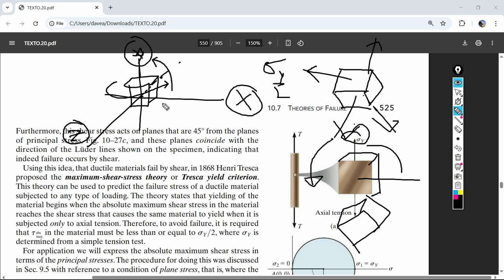Nothing changes there though. So yes, you could do that if you had biaxial, but because this stress is 0, your principal... So I could say this box. Sure, this is a big number. This is 0 in that direction, and then out of the page and into the page is also 0. So when I rotate it about the y-axis, just horizontally, these are my principal planes, so Mohr's circle still applies.